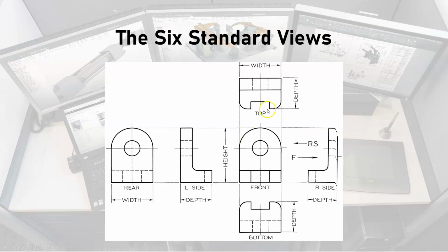Note, though, the alignment of the views. This is very critical. The views always must align. So we have an edge coming down here. In fact, this edge in the top view is this edge in the front view, is this edge in the bottom view. So the views align because we're talking about the same edge. The bottom surface here is this bottom surface, is the same thing here, and is the same thing here.